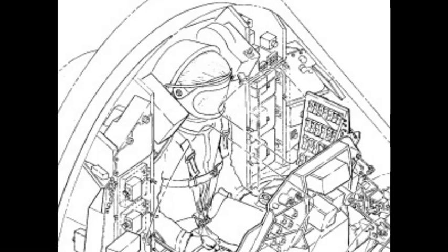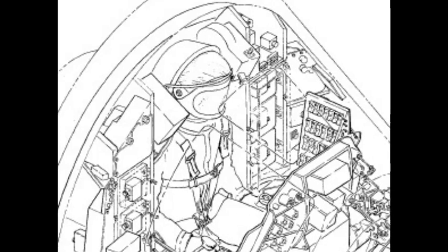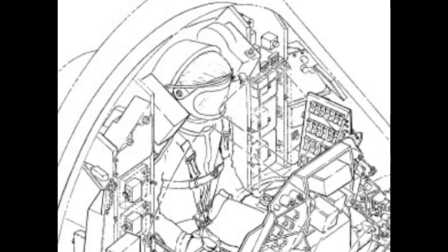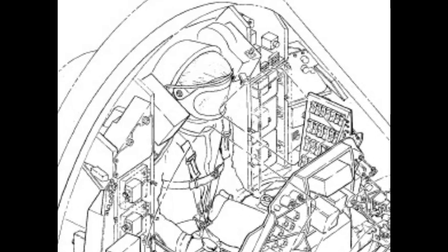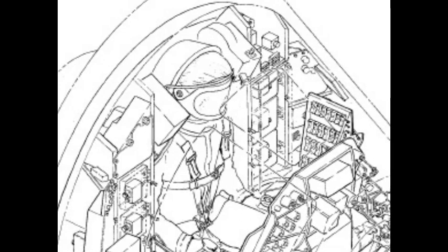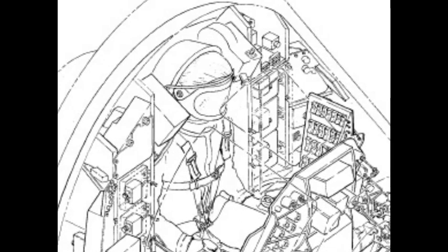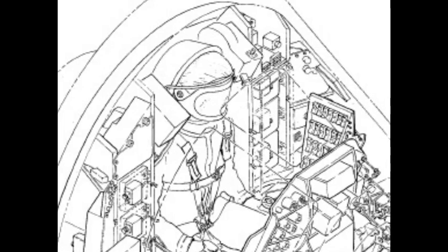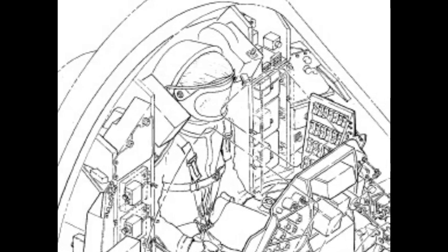The bolts are fired to separate the clamp ring when the pylon is jettisoned from the capsule. During capsule normal launch, the escape and jettison rockets are fired simultaneously to separate the pylon from the capsule. In the event the capsule escape system is activated during launch phase, the escape tower is fired to propel the capsule away from the missile, and then the jettison rocket is fired to separate the pylon from the capsule.